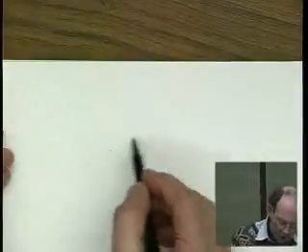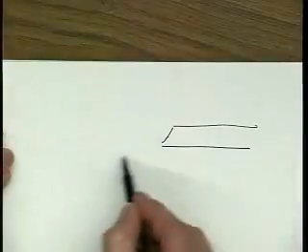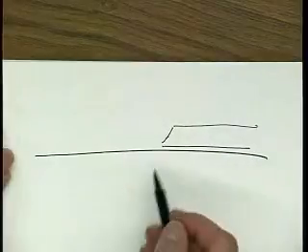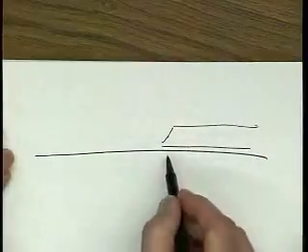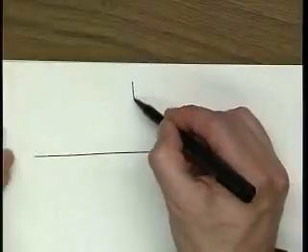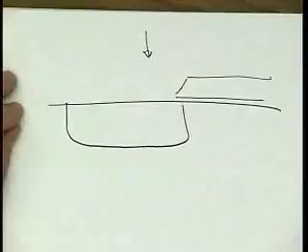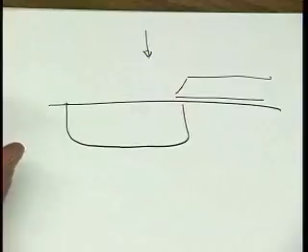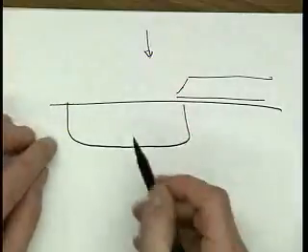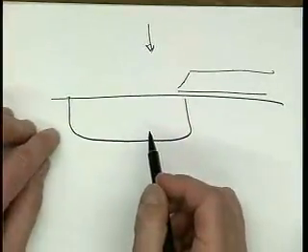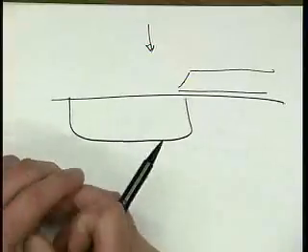What is that? Well, here is our transistor. And the way it's made is that we use the polysilicon as a mask, and then we use an ion implanter, and it shoots ion into this thing, and it makes the source or the drain. It looks like this, right? Now, the source or the drain, the doping has gone up. Now it's 10 to the 20th, 10 to the 21st, whatever, right? It's almost a metal. So it's highly doped. But nevertheless, the sheet resistance here is fairly high.